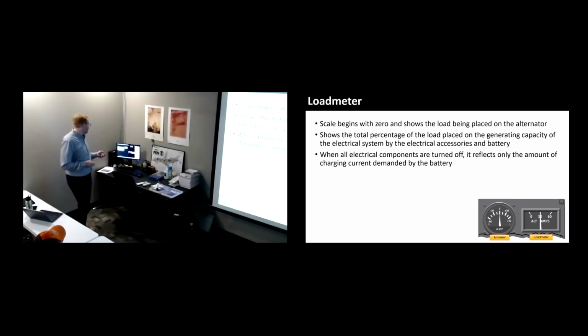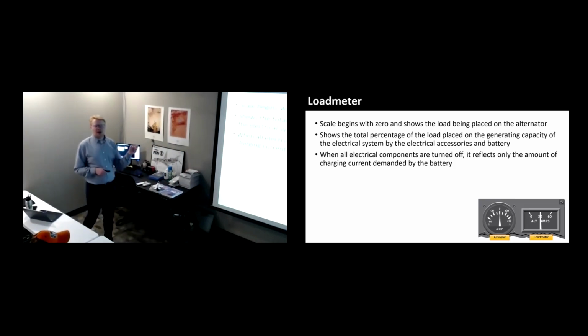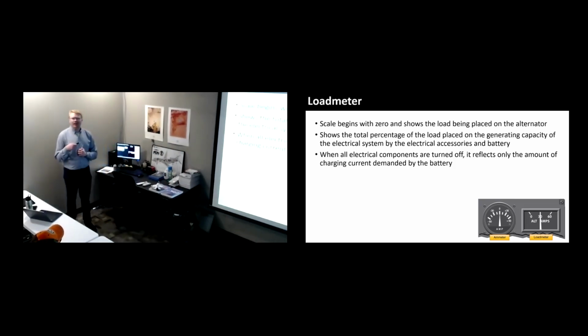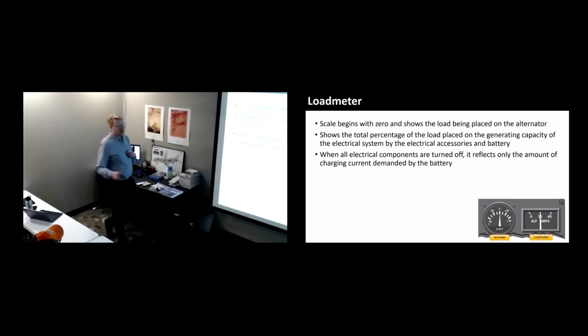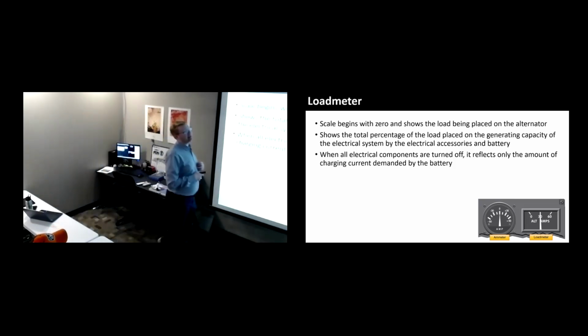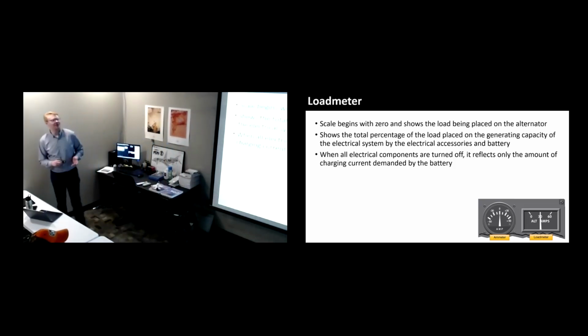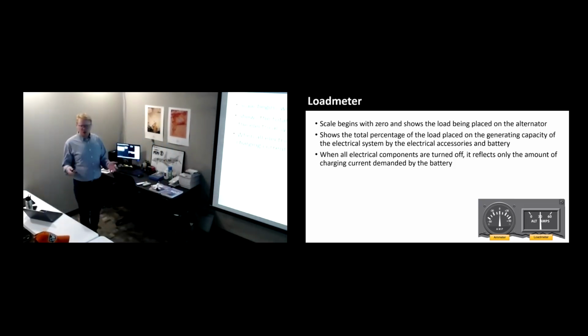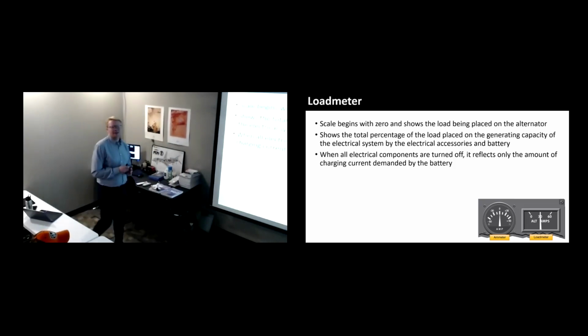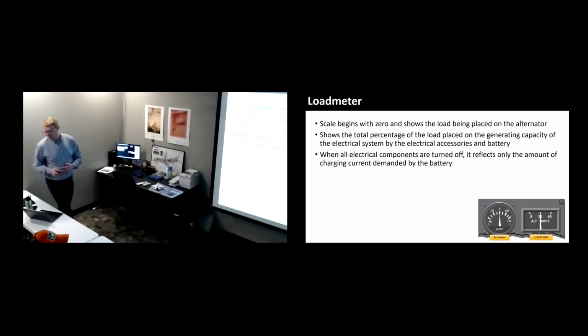In the Cessna 172, I don't see a picture here. There's a separate bus, separate switch for avionics. Many airplanes do. That switch powers the avionics bus bar. In a Cessna, I can't tell you exactly off the top of my head, but there are multiple avionics buses for different purposes. There are multiple main buses for different purposes. But when we turn the battery on, it usually powers most of our essential equipment. So we got that turned on.